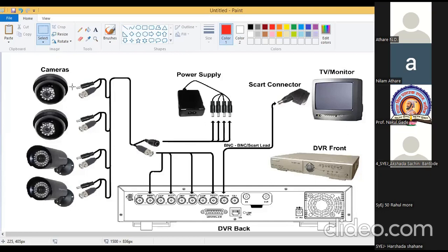If you want to see only camera 1 data on your whole monitor, you will select that IP address, and then the data will be given to the PC. If 2 cameras are given the same IP address, what will happen? The IP addresses of the 2 cameras will conflict, and data will not be recorded. So IP address allocation is an important thing.